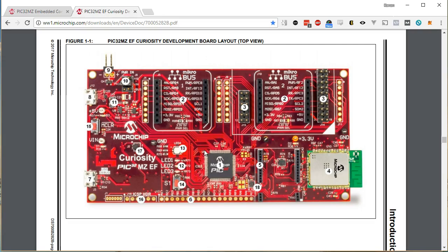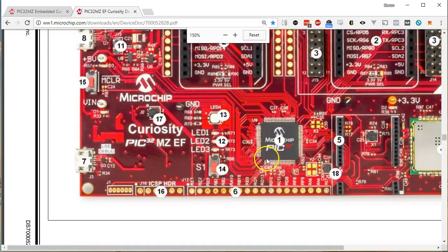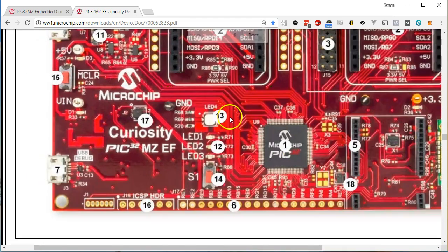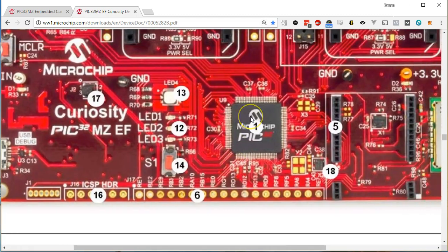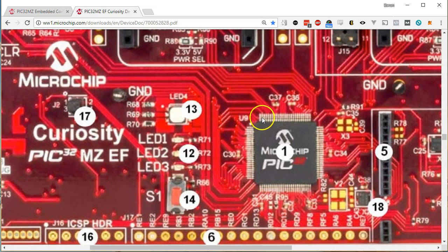But essentially, if you zoom in here, it makes more sense based on the schematic that these two pins are associated with the LEDs, because it's this one right here, so these two leads. You can see that they come over to right here, and most likely they just via down and right here. So they run through a resistor and then through the LED, or through the LED and then through a resistor. Most likely via or something like that.